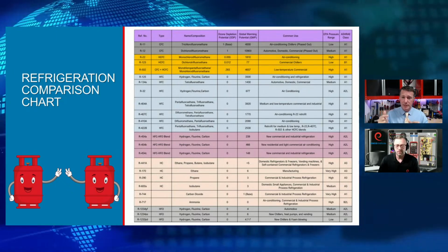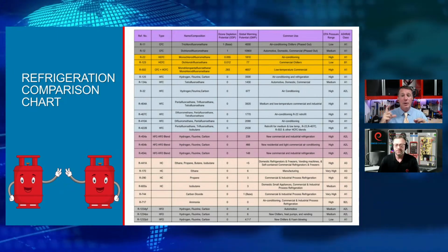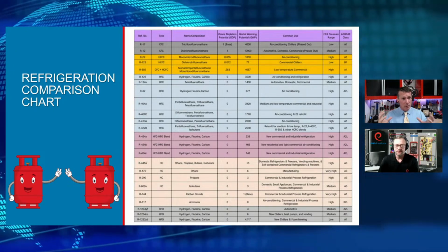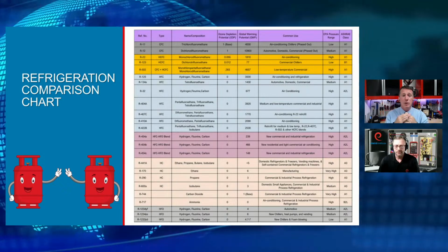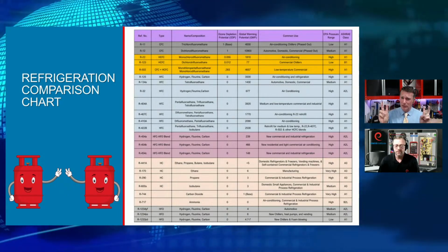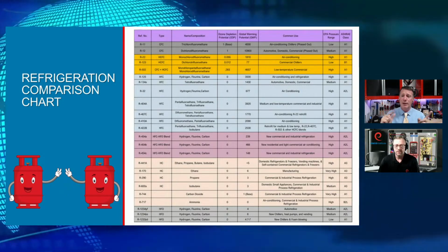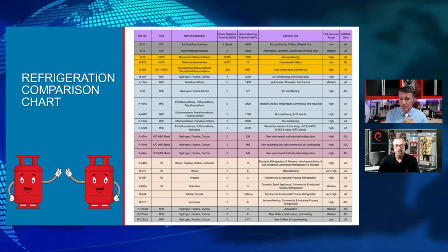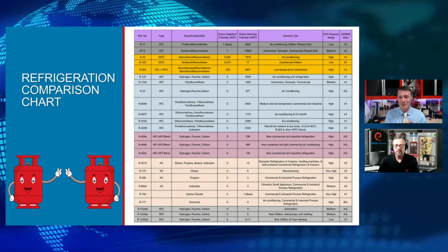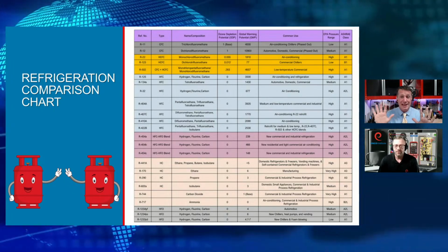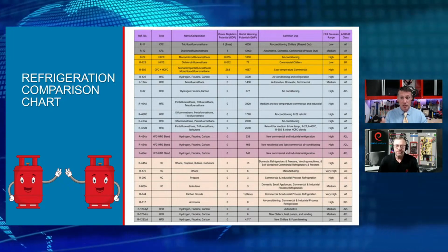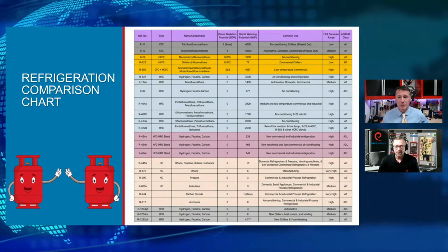So as we move into these new classes of refrigerants like A2, A2L, and A3, we need to be prepared for where we're going to see them, because they are going to be in some pieces of equipment that look similar to each other but might be for very different applications. Some may not even be allowed to be installed under local building codes. So we may see two different classes of refrigerants in a very similar piece of equipment based on your location. Is that some of the things that you hear, Jason?